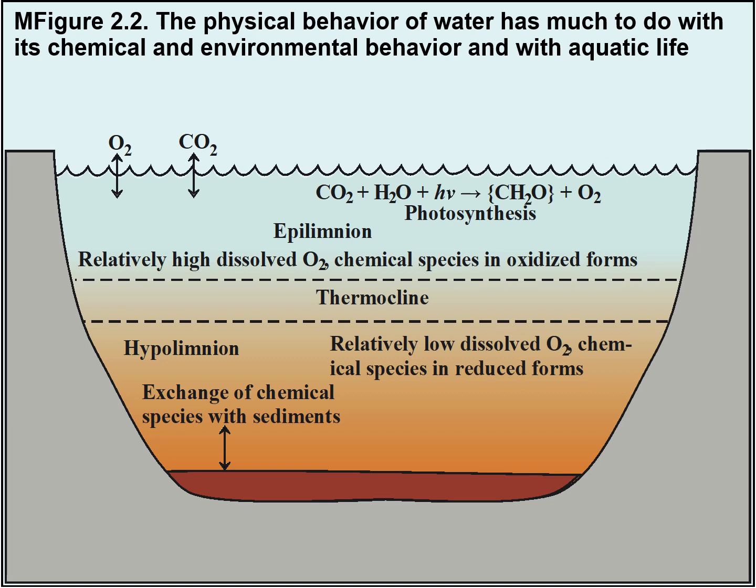And because the top layer of water, the epilimnion (epi means above, and lim refers to the surface waters, like limnology), is actually separated from the lower layer, which is called the hypolimnion. Remember, hypo means below, like hypothermia or hypoxia. Since those are separated by a thermocline, a significant temperature gradient, the waters aren't going to mix, and they actually have separate equilibria that govern sediments. We'll again mostly need to use molar units to talk about all of the things that will be in equilibria.